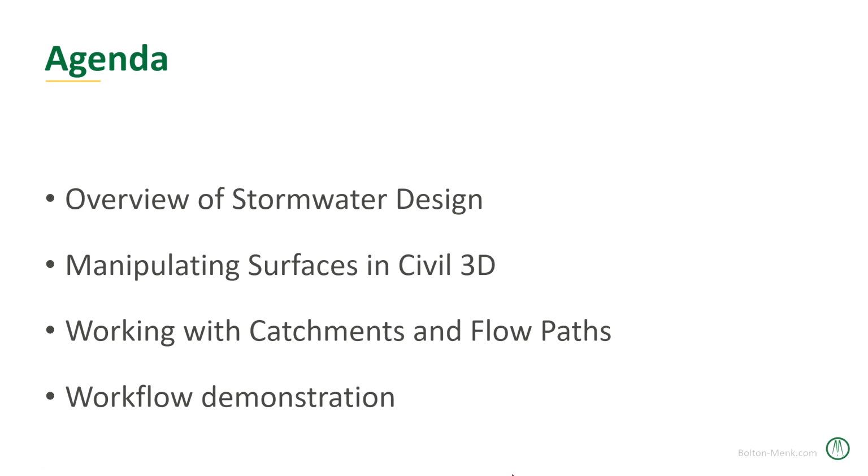As far as today's agenda, the first thing that we're going to do is run a brief overview of stormwater design. Yes, this is a complicated field of study. There are entire conferences for this. We'll just standardize some vocabulary and review our basic goals. We're not getting into any sort of calculation methods today. Once we're done with that, we'll go over what we need to know for manipulating surfaces inside Civil 3D. Then we'll talk about what we need to know for working with catchments and flow paths, and then I'll do a workflow demonstration where we'll look at a site and start playing around with this to get a drainage exhibit put together.